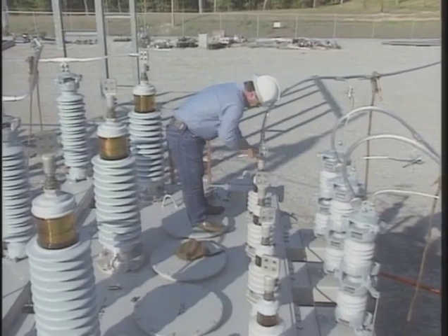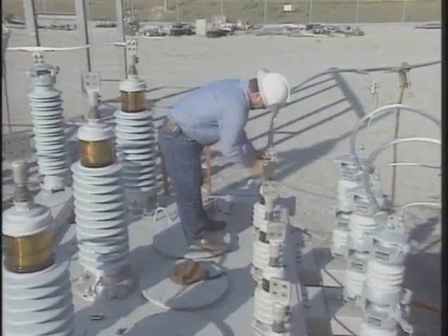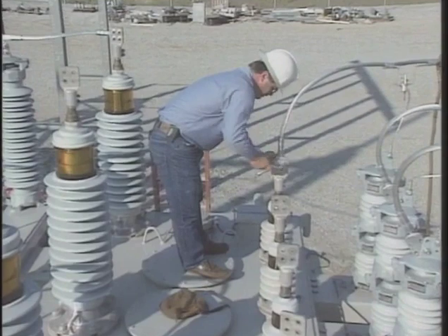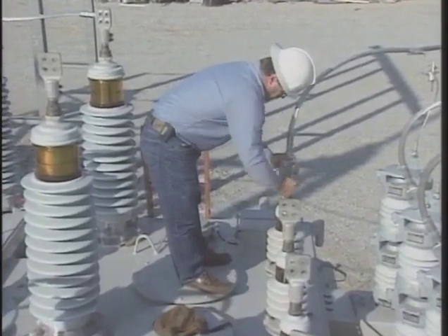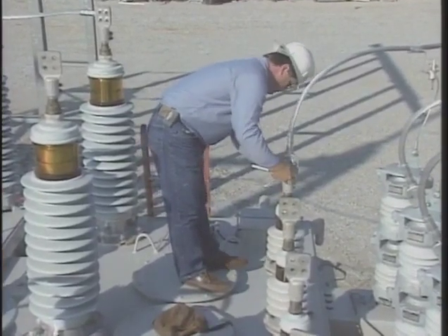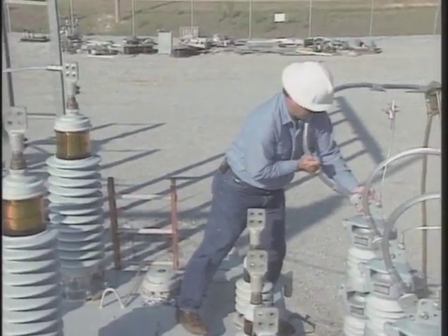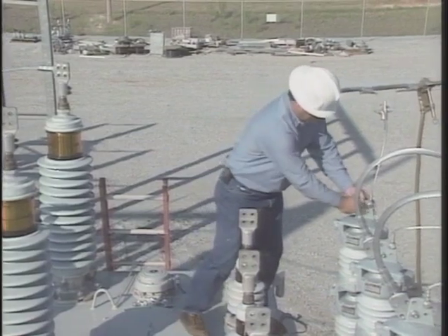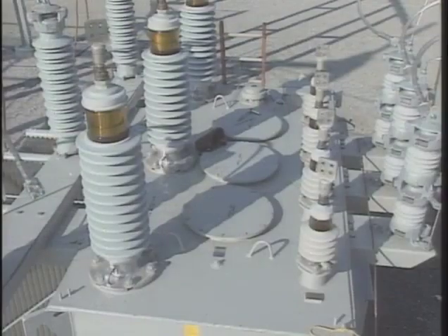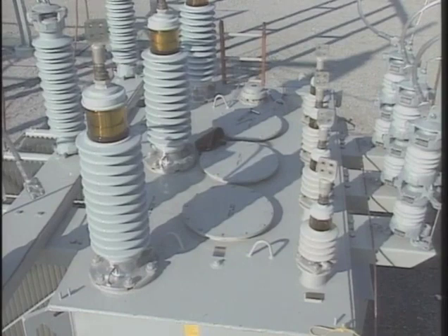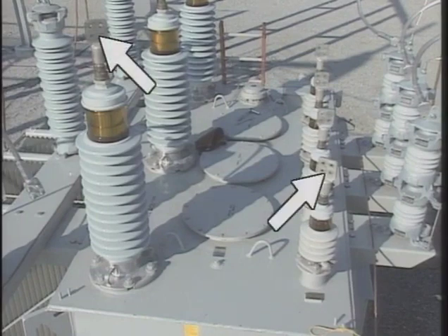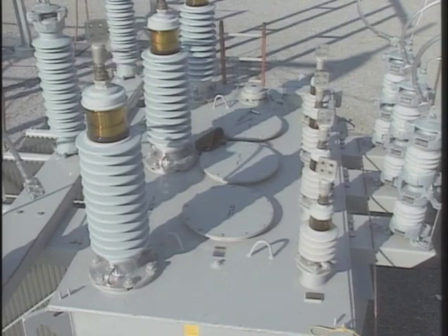Once the transformer has been made safe to work on and the area is secured, specific preparations for testing can be made. For example, the grounds are removed from the transformer just before the turns ratio test is performed. This is typically done by lifting the conductors from the transformer terminals with the ground still attached to the conductors. However, if there's energized high-voltage equipment nearby that may induce voltage in the transformer windings, it may be necessary to keep a ground on one end of the high-voltage winding and on one end of the low-voltage winding that are being tested. All other grounds would be removed.